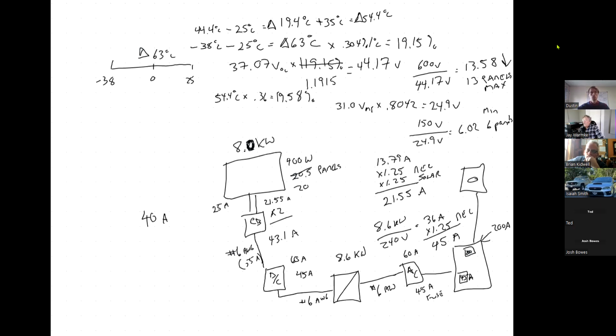Well, one choice, and you're seeing this increasingly, oftentimes these service panels are rated for 225 amps, not 200 amps. Well, what's 20% of a 225 amp panel? 45. That's cool. If that were the case, if it was a 225 amp rated panel, I'm fine.